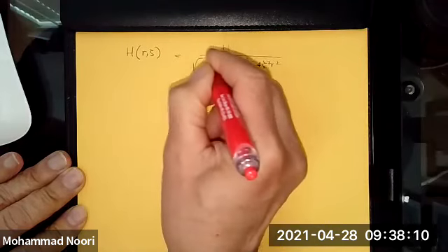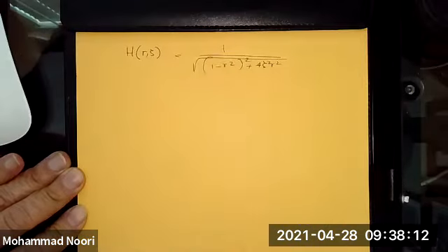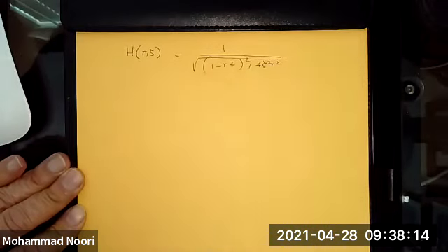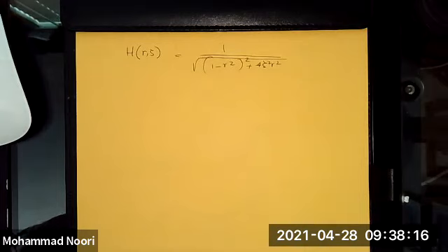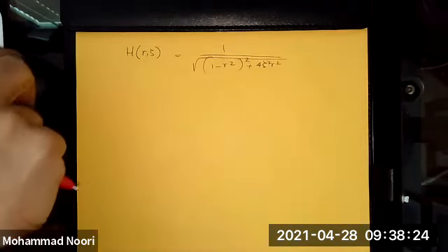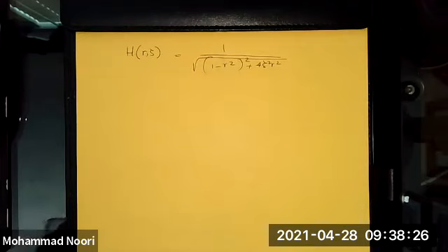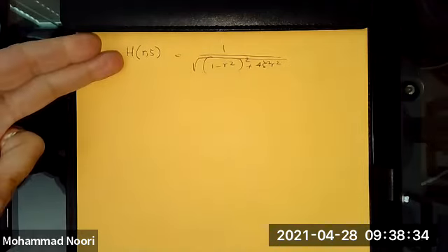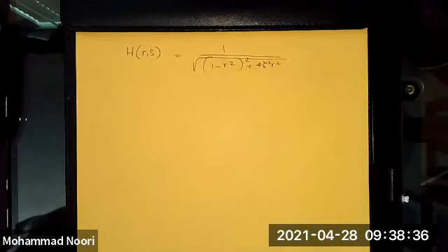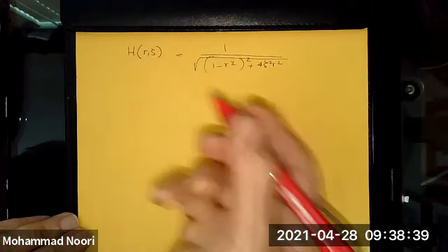So let's go back to the first claim that I made, that as damping increases, you see the shift of the peak toward the left of R equal to 1. And then I claim that if damping goes beyond 0.71, this H value is always less than 1. So let's prove those.